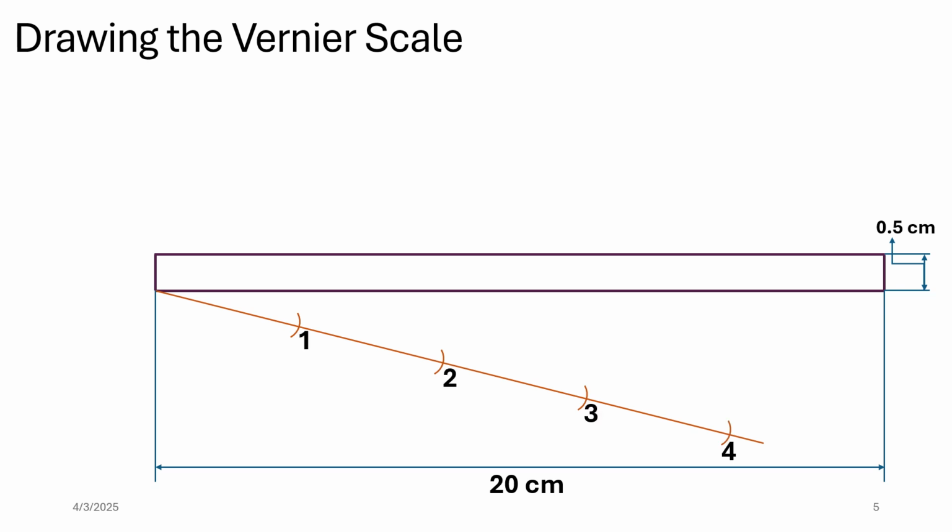So these are 4 arcs, and from this one we join the last arc to the last point of the scale. Then from other points draw lines parallel to this one. This divides our scale into 4 equal parts. So this is giving us our 0, then 1, 2, 3 meters on this side, and then 1 meter on this side. Once it is done, then we need to divide this first one and in fact all the ones into 10 more equal parts.